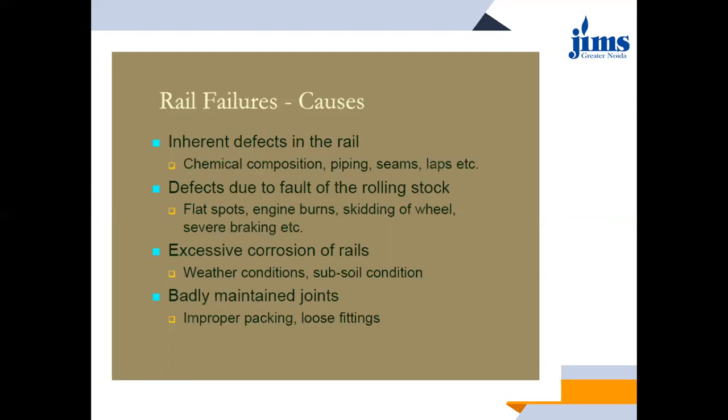These failures caused by faults of the rolling stock are listed as flat spots, engine burns, skidding of wheels, and severe braking.